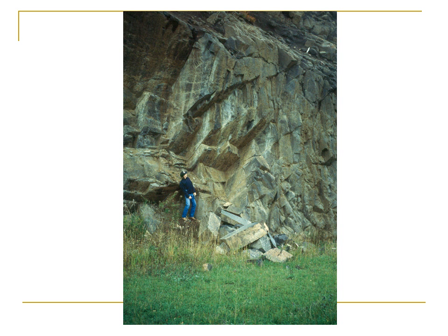Here's one where you see 3 different discontinuity sets in this rock slope that combine to create this sliding mass. There's the toe of the slope there that you show as the lush green. That's what's left after a U.S. highway was removed from the base of the slope, and it was decommissioned due to the number of deaths that occurred as a result of the slope failures along this roadway. After rainy seasons, the blocks would be out on the roadway, causing a number of deaths over the years in traffic accidents.